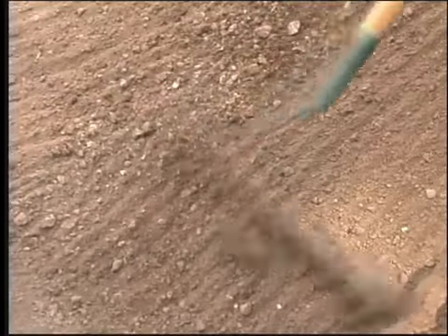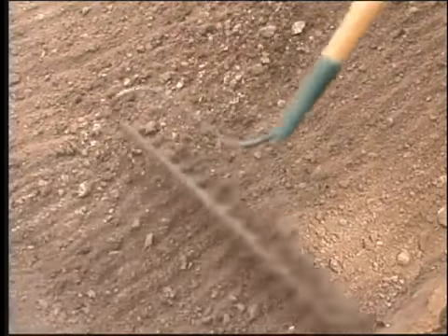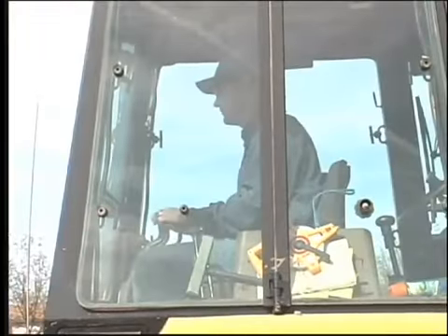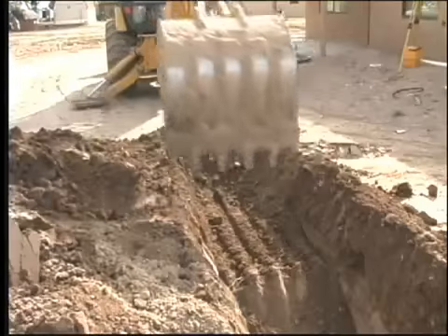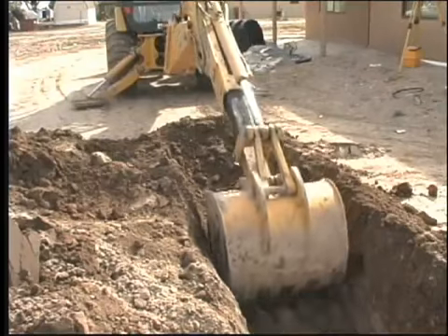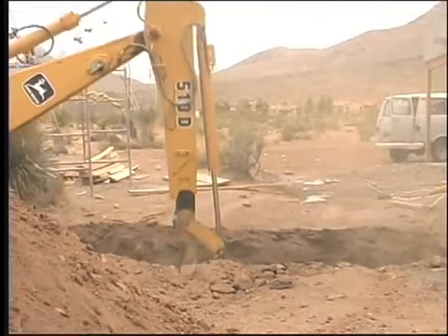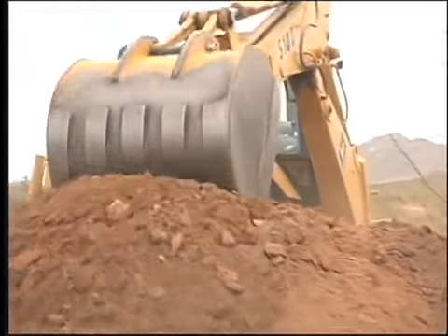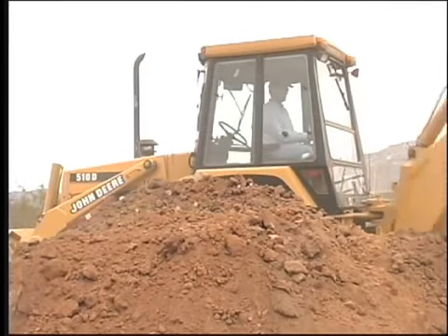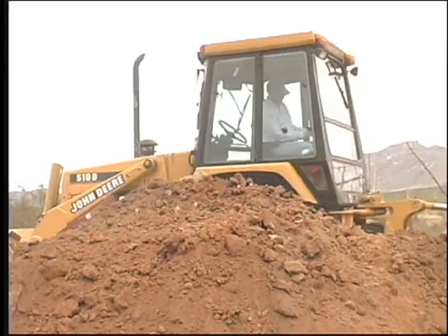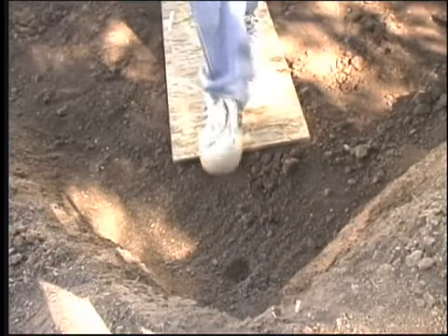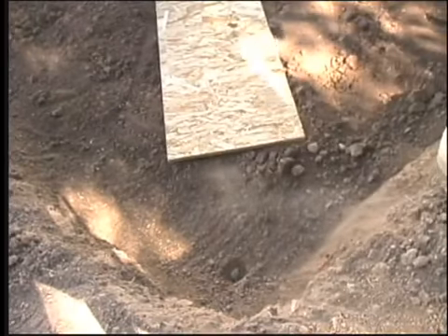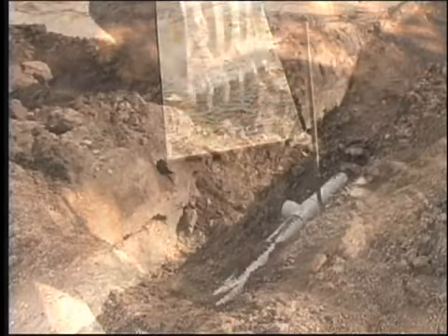It is critical that the teeth of the rake penetrate well into the surface and break up any smearing of clays that might be present on the surface of the soil. If you use a backhoe, attach fabricated raker teeth to each side of the bucket. Keep the backhoe bucket perpendicular to the trench bottom to minimize compaction. If the soil is sand or caliche, it will not be compacted, so there's no need to worry about these issues. To prevent further compaction, try not to walk on the finished trench bottom. If foot traffic is necessary, use planks to spread out the worker's weight.